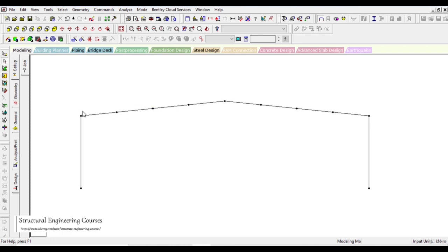That is, the height of this beam is maximum here because the bending moment is maximum here. After that, it somewhat reduces here, and then it again increases here because this is the negative bending moment that is maximum. Here this is the positive bending moment that is maximum, and the negative bending moment is approximately much higher as compared to the positive bending moment.